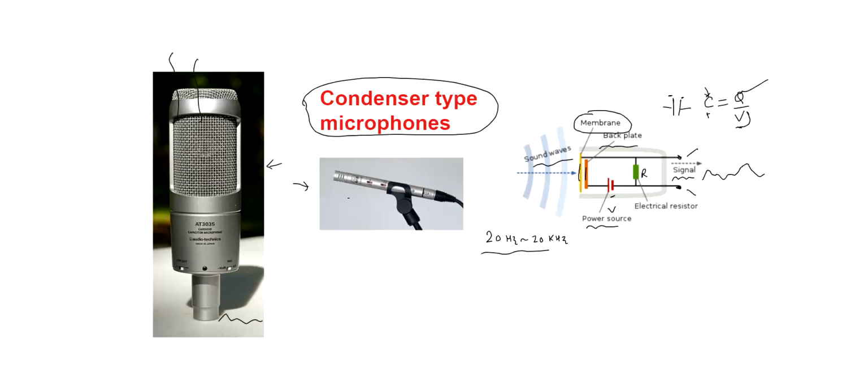So R and C, the value of the capacitor and the resistance. The resistance is usually hundreds of mega ohm or in the range of few giga ohms. And your capacitance is between 1 to 10 picofarad. Okay, so resistance is hundreds of mega ohm to giga ohms. So you have a large time constant, so very low frequency actually.